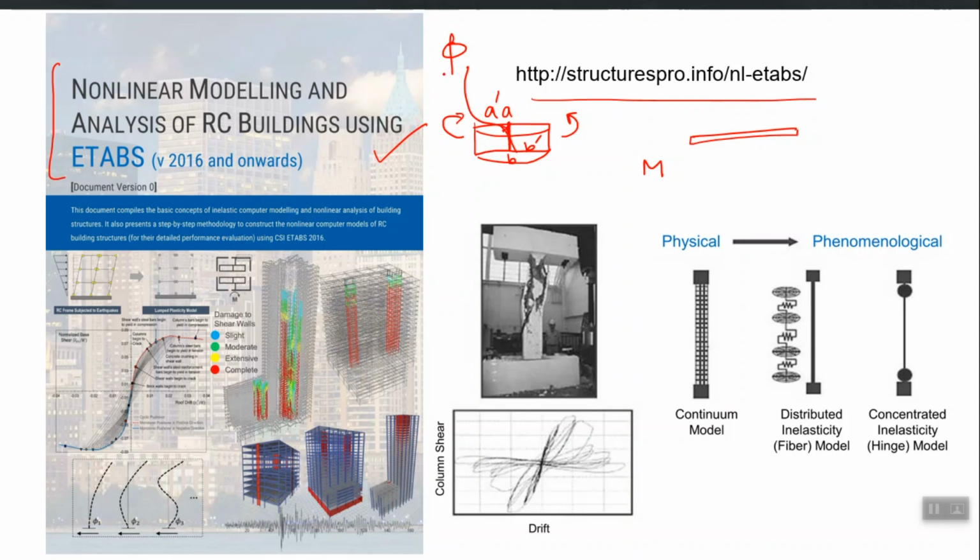So curvature is actually a cross-sectional deformation, which is the deformation associated with bending moment, right? So moment has an effect called curvature. So moment is related with curvature, just like stress is related with strain, right? Torque is related with twist angle, let's say theta. Similarly, shear force is related with shear deformation. Moment has a deformation which is curvature at cross-section level and rotation at member level.